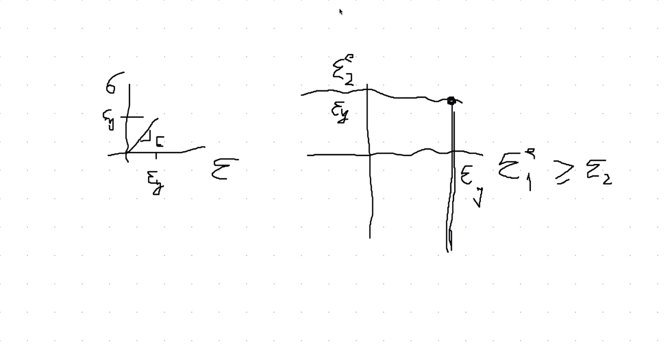And then how do we go to stress values? Well, you write that sigma 1, sigma 2 in terms of the principal values is equal to a matrix, lambda plus 2 mu, lambda, lambda, lambda plus 2 mu, if I use the Lamé parameters.